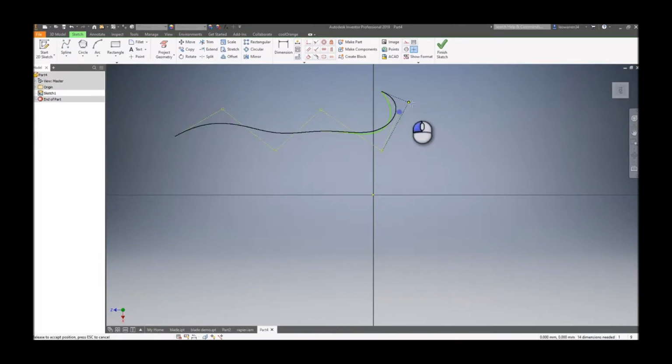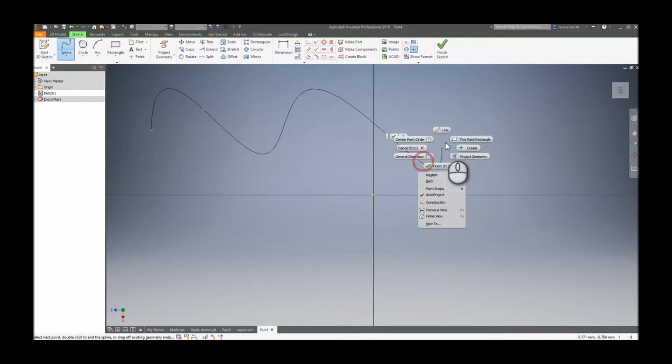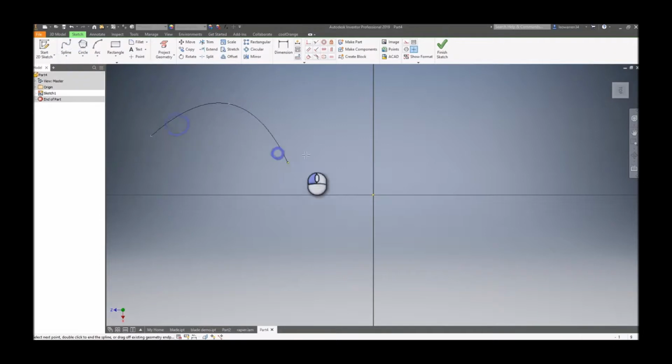The control vertex gives you these little points that you drag around to actually modify it. The other type is called interpolation, so if you drag it, instead of dragging the points outside, you have to drag the little squares here and drag them around, and that'll do it.